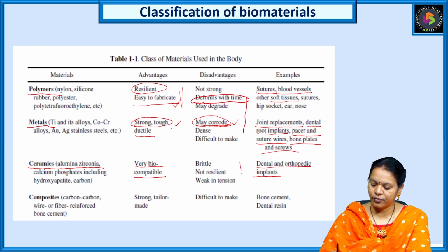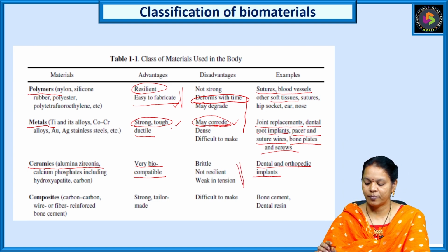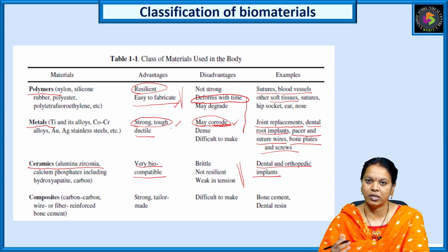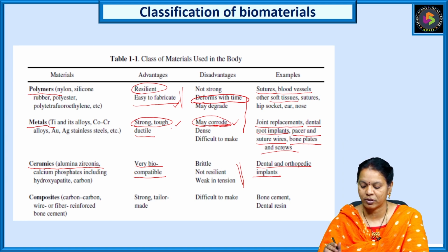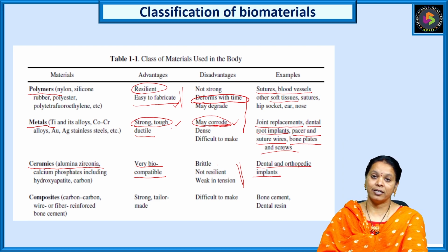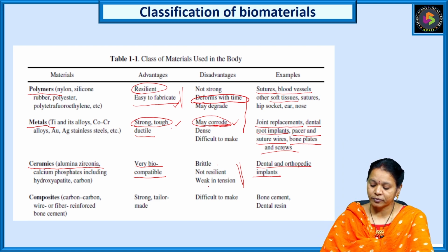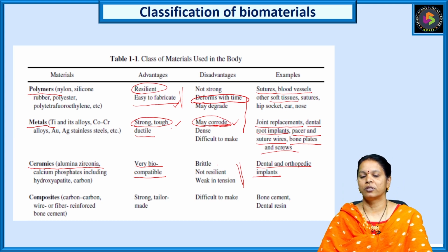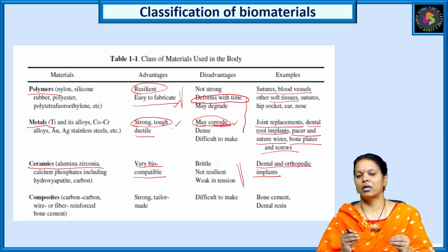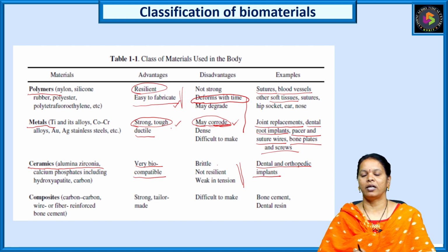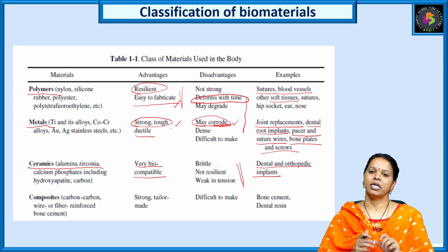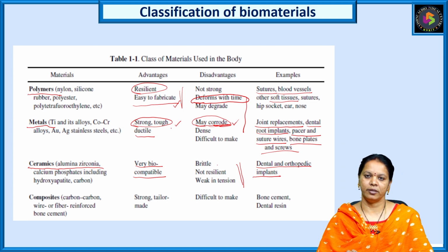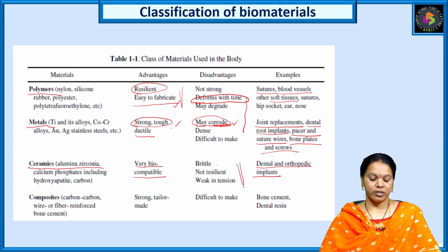So there are also a few disadvantages with ceramics. Because of these modifications and the different fabrication technologies, in the process they become brittle and they are not that resilient to fabricate. And compared to compressive forces, tensile forces are very weakly handled, and in the case of torsional forces, they tend to break and become brittle. So these are the disadvantages with ceramics.